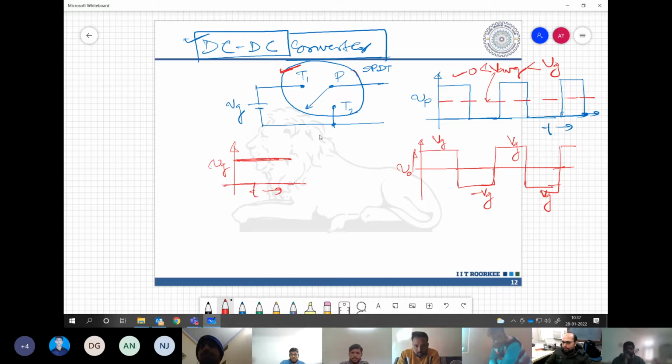Because here power flow will always be from DC to AC side, considering simple motor operation. But because of inductive nature, the current sometimes will be lagging. So during that time, we need both directions of current also, sir. Bidirectional current is okay, but don't say bidirectional power as of now. Bidirectional voltage and current, sir, not power.